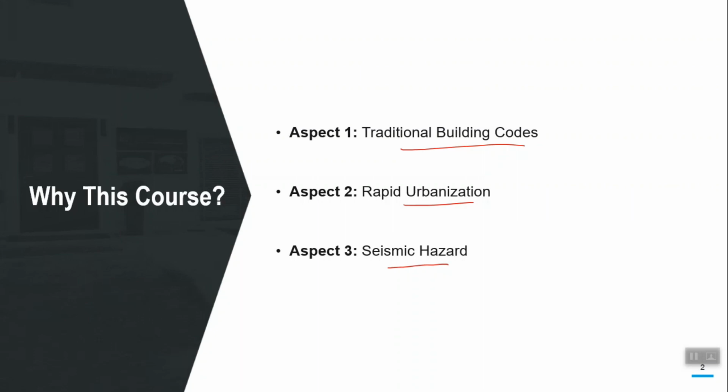The basic idea of this approach is that a decision maker sets a performance objective and the engineer follows and fulfills that performance objective, and in doing so he uses advanced analysis and design procedures. He is free to use any alternate approach, if it is approved by an authority having jurisdiction. So, if that approach is approved by the authority which is regulating the structural design at that particular site, you are free to do that. It is not necessary to follow the letter of a particular building code if you are going for that alternate approach. This is the summary of this approach.